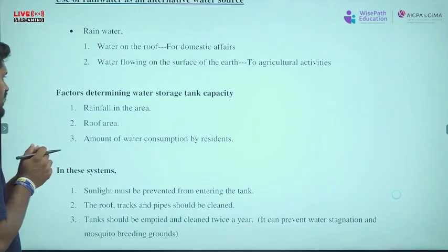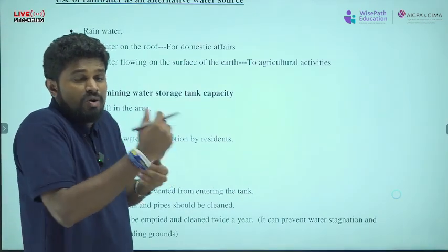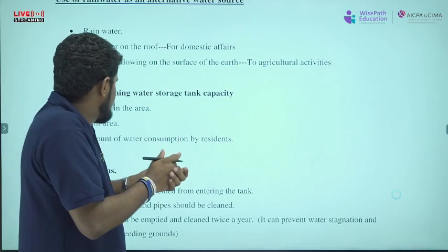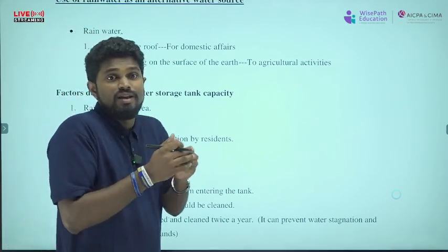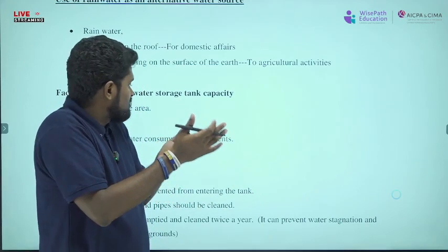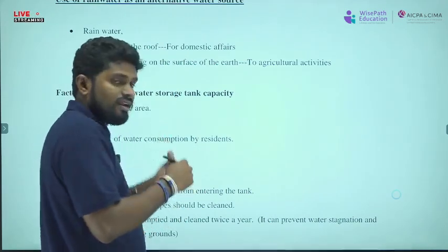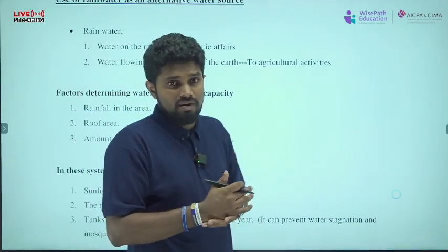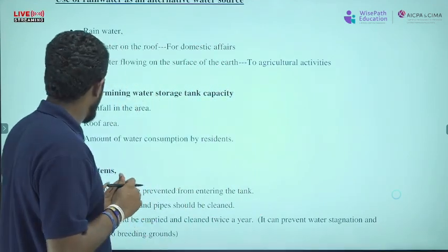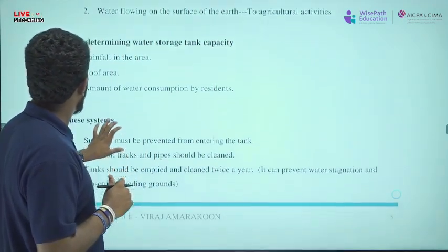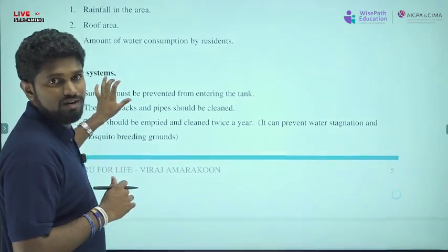Okay, and if the roof area is higher, you can collect more water, then you have to increase the water storage capacity. If the amount of water consumption by the residents is higher, then you have to increase it, no? They consume more water, no? And if rain happens rapidly, or it rains a lot, then you can collect more water, no? Yeah, those are the factors to consider for the storage of the water tank.